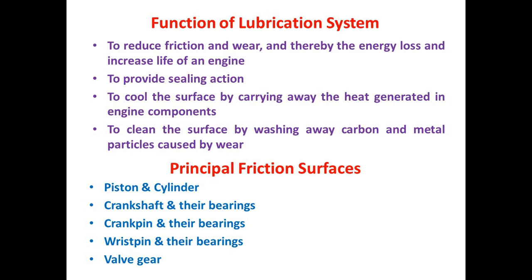The second function of the lubrication system is to provide the sealing action. To be specific, lubricating oil helps the piston rings maintain an effective seal against the high pressure gases in the cylinder. Definitely these high pressure gases occur inside the cylinder after the combustion. So, to avoid leaking of these gases into the crankcase, oil sealing is useful in the case of the piston.